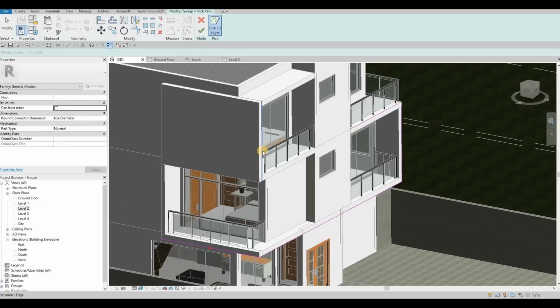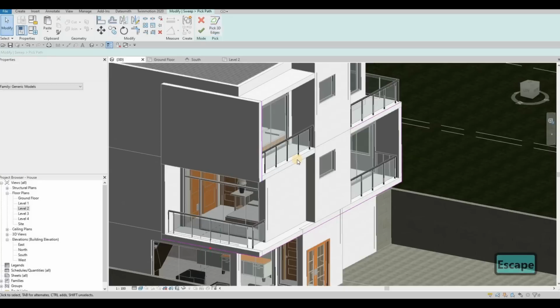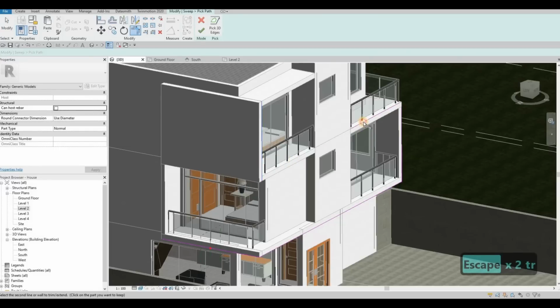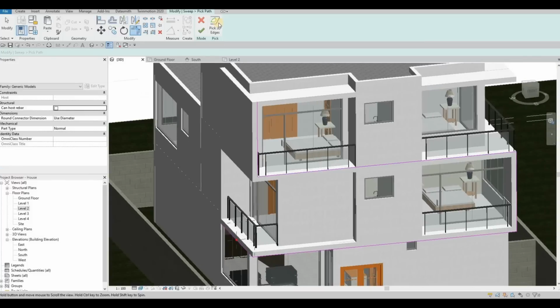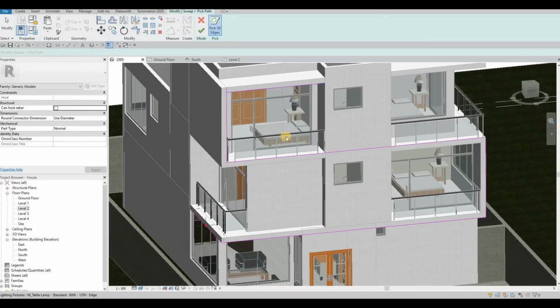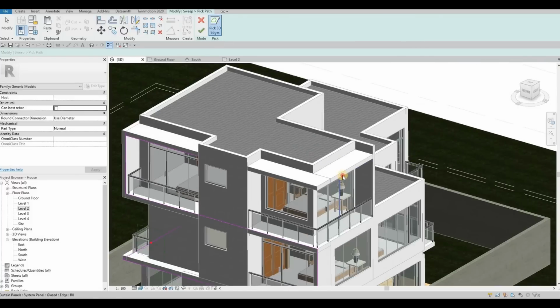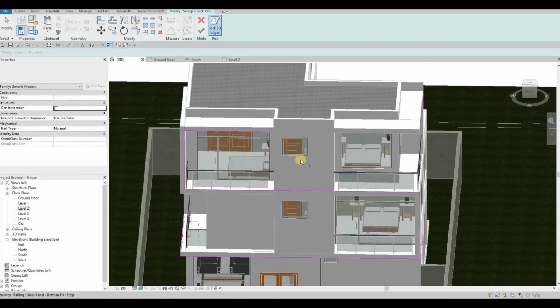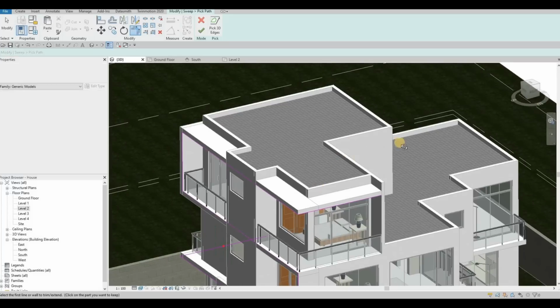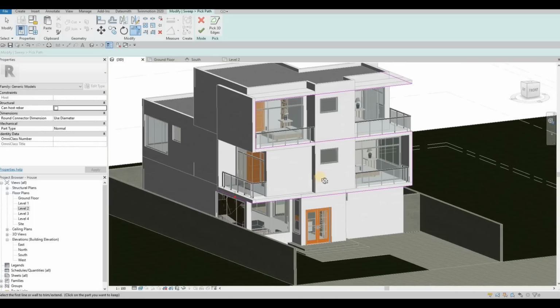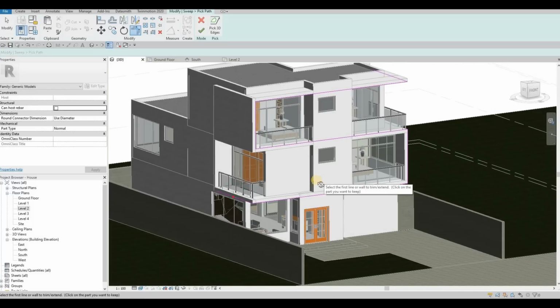And then from the inner side to the outer side, everything is connected. Pick again here, all the way on this side. So trim it, TR, here to be connected, and then I think everything is looking good.